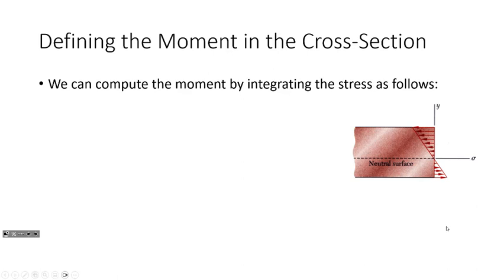Then as you get away from the neutral axis, it either experiences compression or tension, right? So here's my little beam. I bend it. The top is smushing together, so it's being compressed. The bottom is being yanked apart, so it's in tension, right? So at the center, we have 0 deformation. As we get away from this, we get compression or tension.